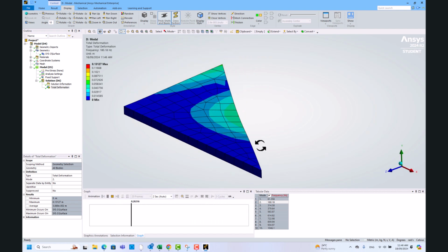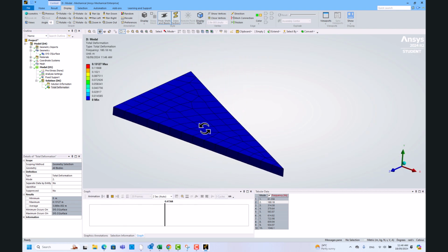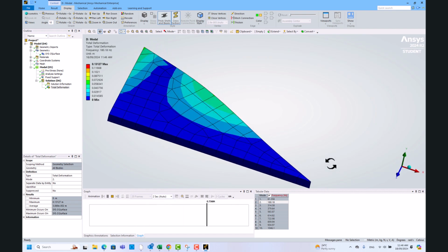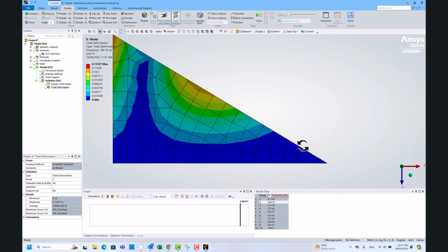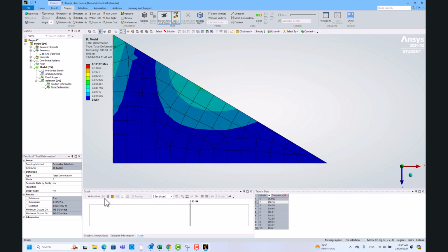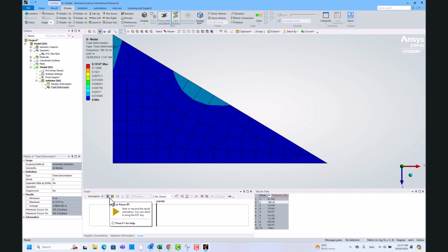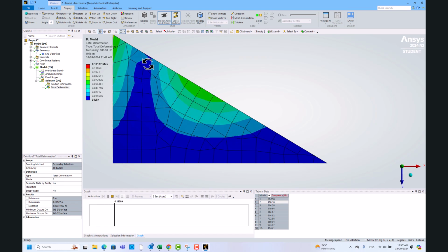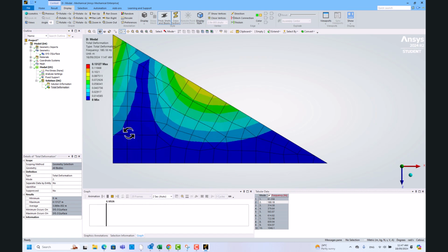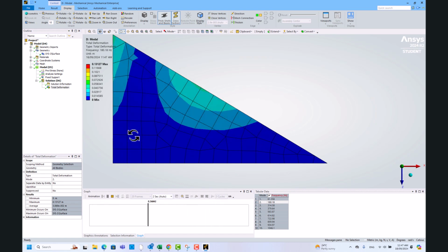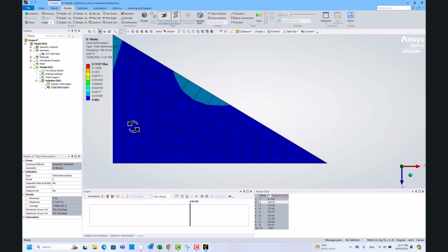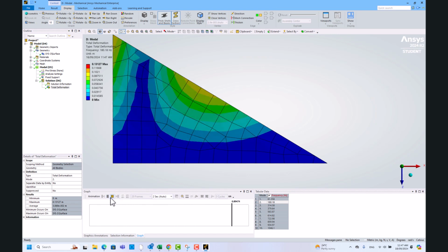And the second mode is doing like that. So it becomes a little bit different to the transverse vibration of a beam. It has a nodal line. Now we call it a nodal line rather than a nodal point, because it has a line that has no deflection.